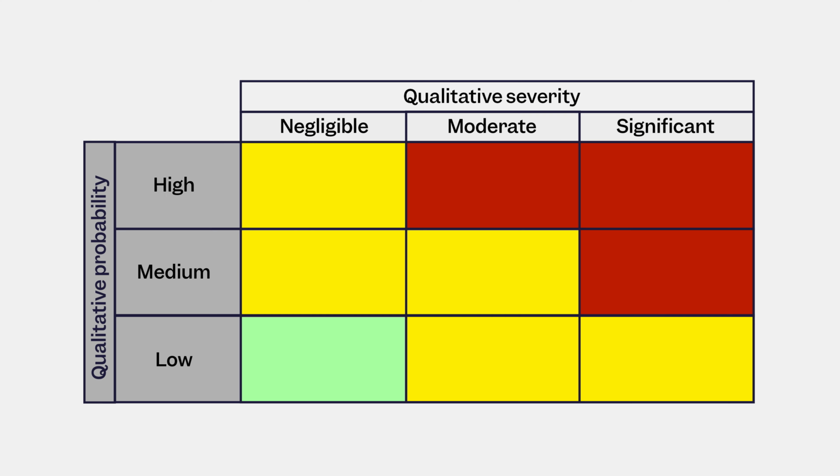The available data and knowledge of the process or device can help the FMEA team rate each potential failure mode and effect. Risk estimation can be done using the quantitative method or qualitative method. The qualitative method can be used when quantifiable data is unavailable. For example, you can use a 3x3 matrix to categorize risks in 3 different zones: high, medium, and low.